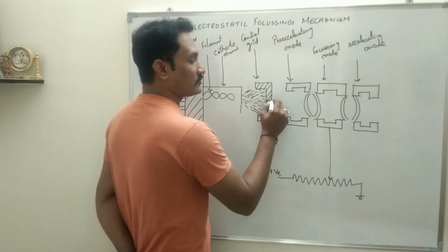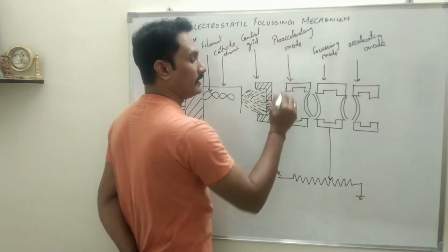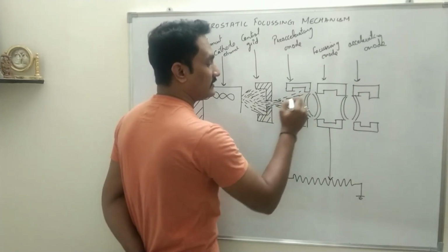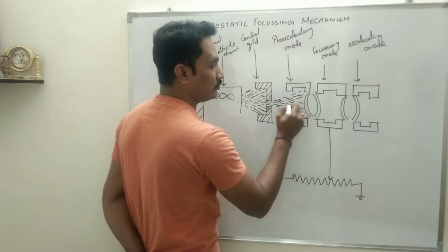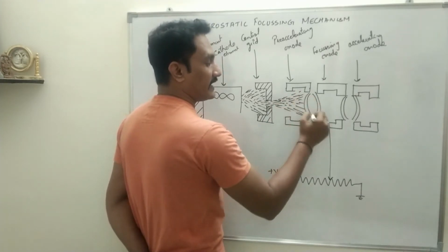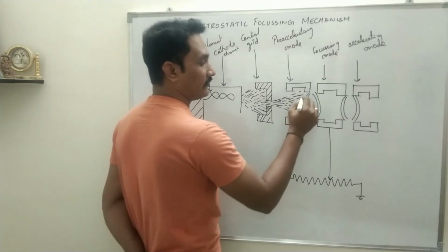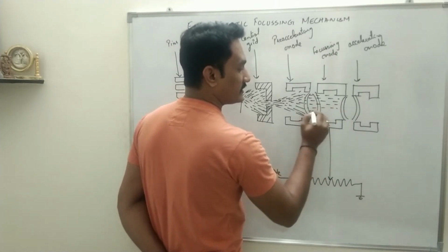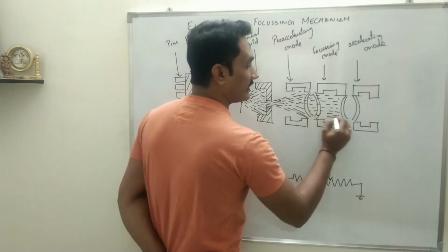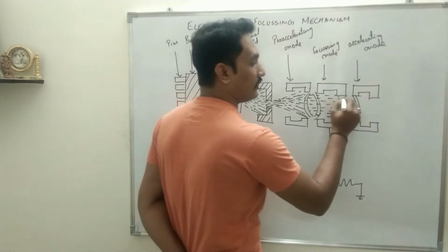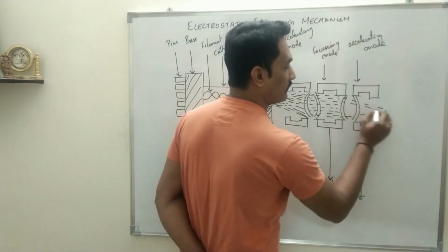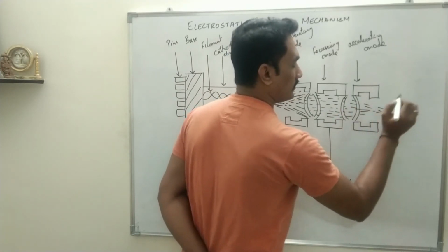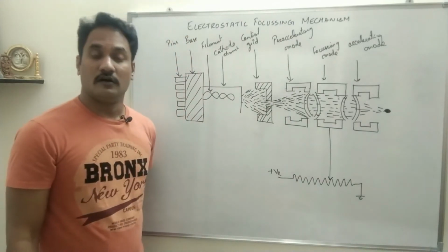Okay, so when the electrons move out of the control grid, they enter the pre-accelerating anode. At the same time, when they enter the pre-accelerating anode, their velocity is accelerated. At the same time, they tend to diverge. When they interact with the first field, all the electrons moving away from the normal are converted into a beam shape parallel to the axis of the CRT. And then when they interact with the second field, all the electrons converge to form a sharp dot of electron beam.